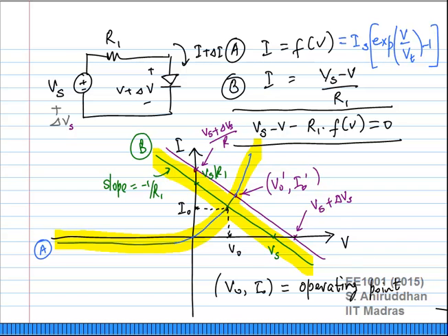The most important thing to remember is that the minute you have a nonlinear element, you can no longer apply superposition. Just because you have applied twice the input voltage, the voltage of interest will not be twice, it will be something else. So you can't do that. And if you apply a totally different voltage, very different from the original voltage, you have no choice but to solve the nonlinear equations once more. There is no other way to do it.